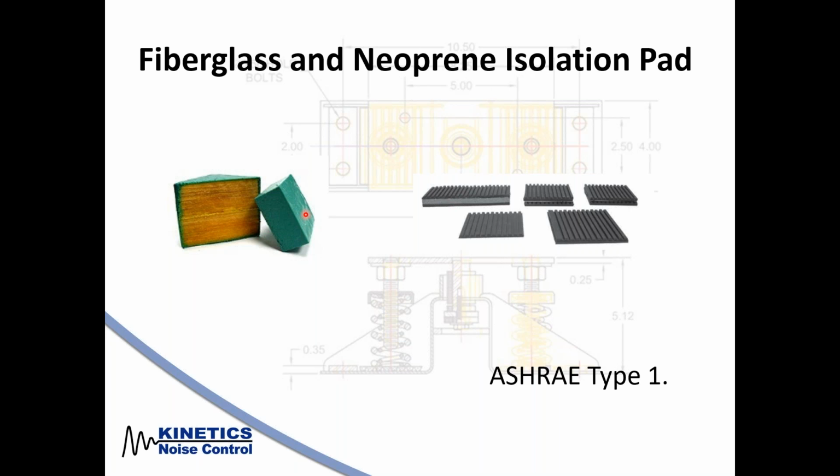Of course, the advantages of fiberglass, it does not get affected by sunlight. UV can't break down the fiberglass over time. It's the very reason we park our campers and RVs and we cover the tires up, so the sun doesn't dry rot the rubber. Same thing with neoprene. That's going to break down from UV. And then temperature can affect rubber and neoprene. In Calgary, for instance, in the middle of the wintertime, a neoprene rubber isolator is rock hard. It's like a hockey puck, and it's not going to deflect. So the isolation is going to travel right through the hockey puck, as it were, as fiberglass is not going to be affected by temperature.